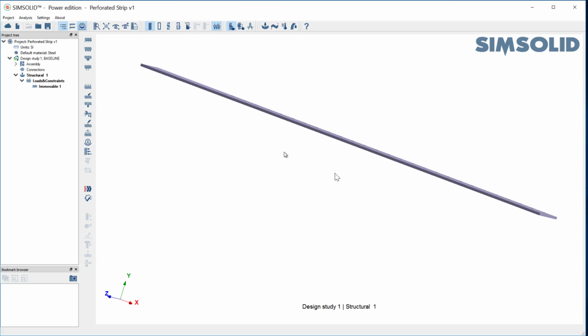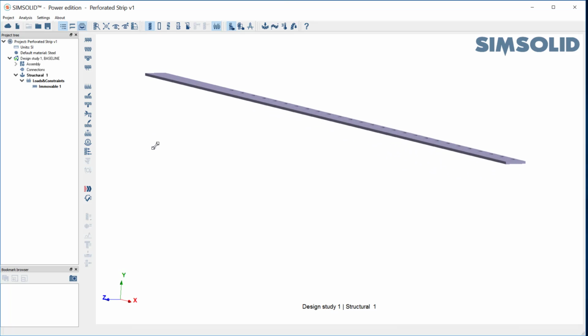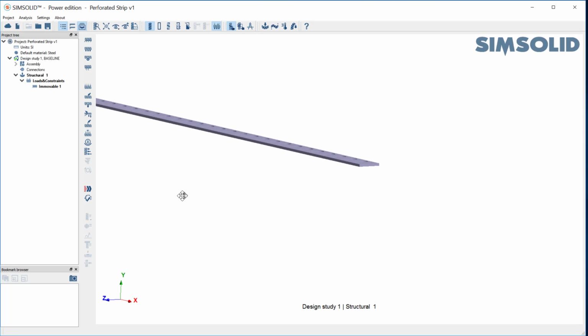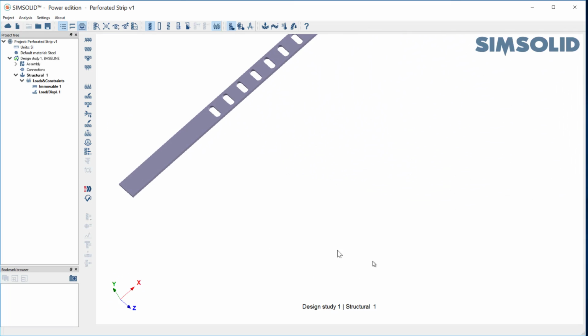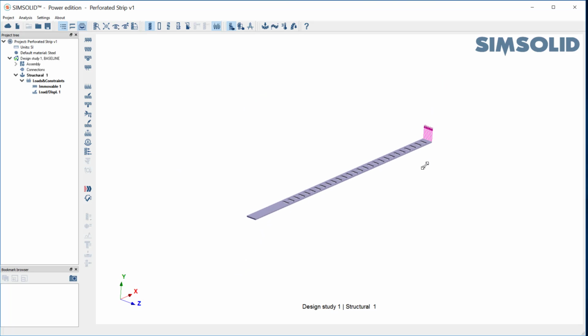Now let's also add a kind of a bending load at the end. So let me come here and put this small area there and put a vertical load in Y. And let's just do 1 Newton. We're going to solve it the first time just in a linear way. So there we go. Okay, so let's try to solve that.